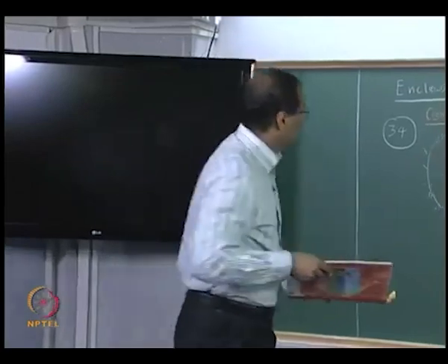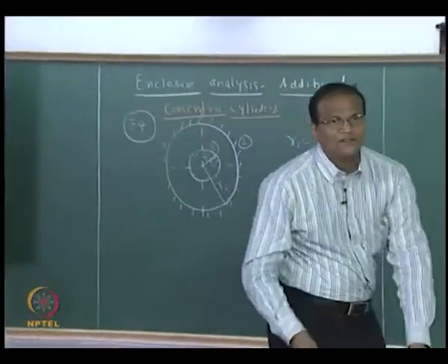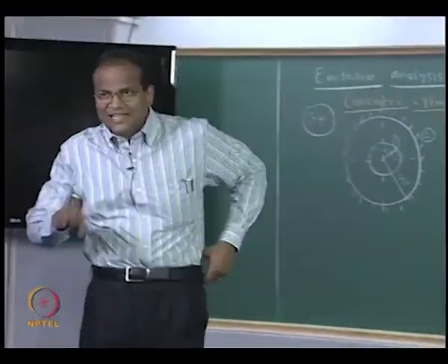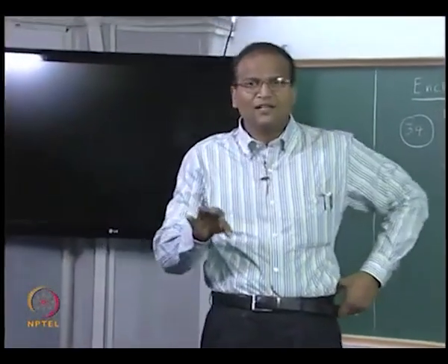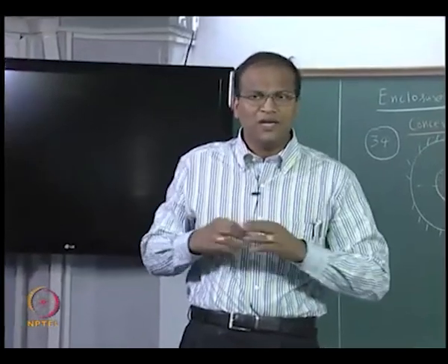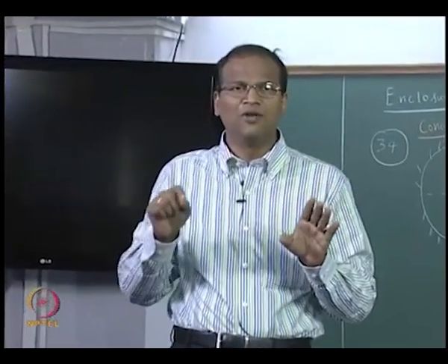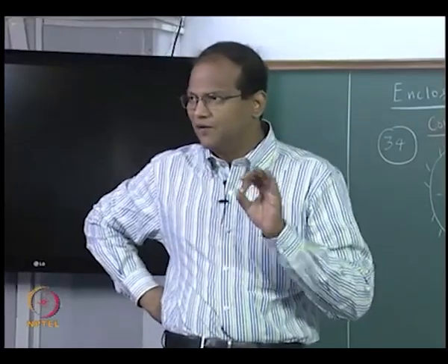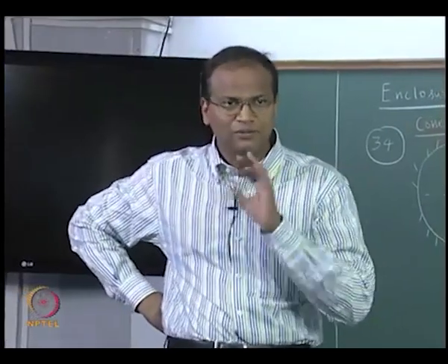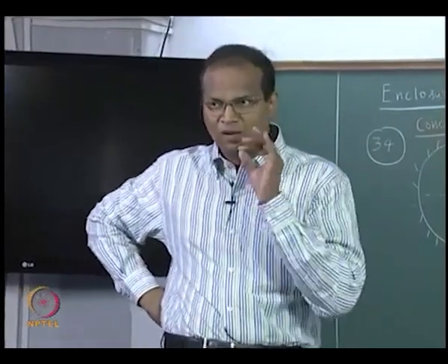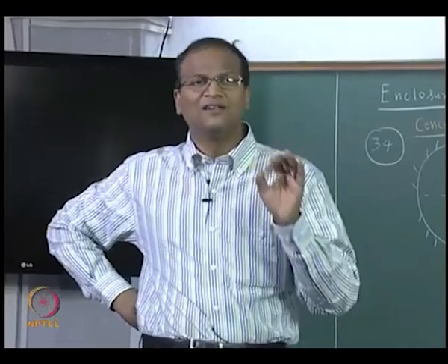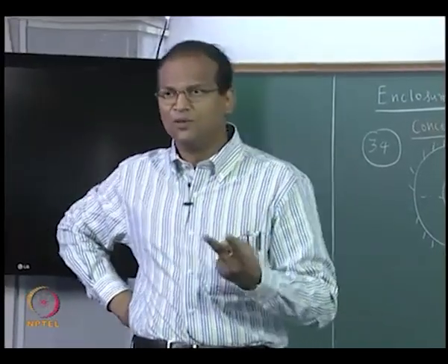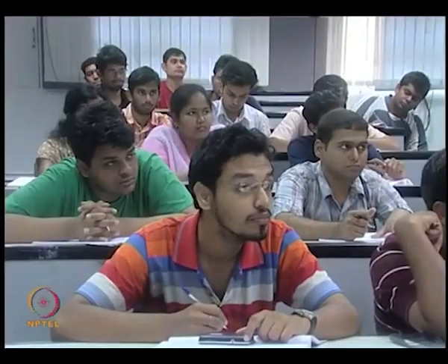Now you can't straight away solve this without first writing the radiosity relations and getting the formula. So a good practice would be, hang on, don't start by putting epsilon sigma T to the power of 4, epsilon 1. I would advise that you keep it as surface 1 and surface 2 with areas A1 and A2, start with view factors, and write expressions for J1 and J2. After all it's a 2 surface enclosure. Then get an expression for Q1.